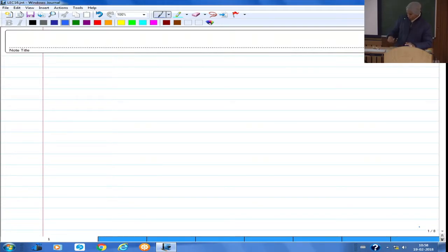So this question was about, actually no, we discussed about frame element. So the frame element means when you have axial as well as transverse load, then you will have to basically model the structure using frame element. But then when to use or how to distinguish between the use of truss and frame element.